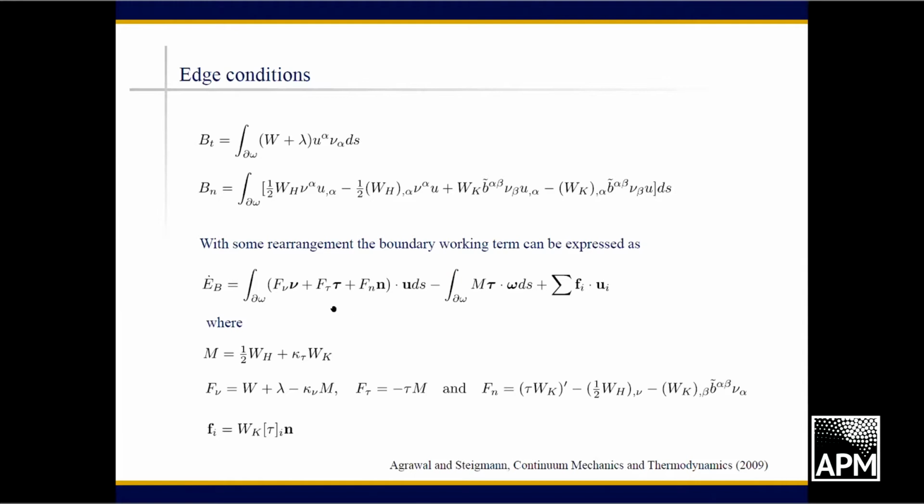If the patch of surface that we're studying has corners, places where the tangent to the boundary is discontinuous, then we also have so-called corner forces at those corners, which are found in this way. And this format is identical to the classical Kirchhoff theory of plates. You may recall from your school days the notion of corner forces in that context, and we have them again here.